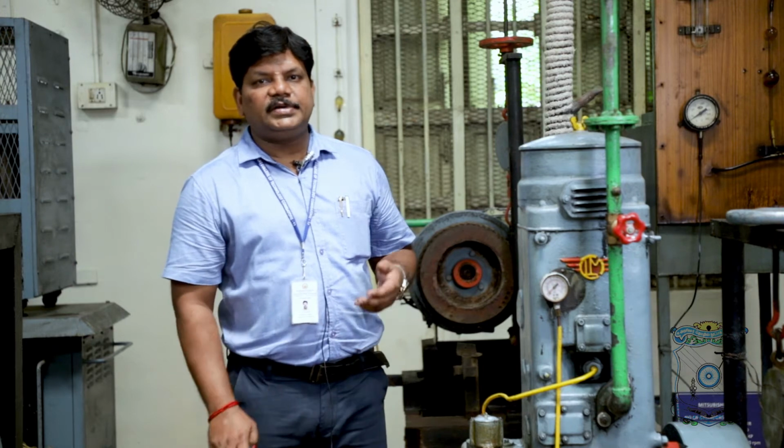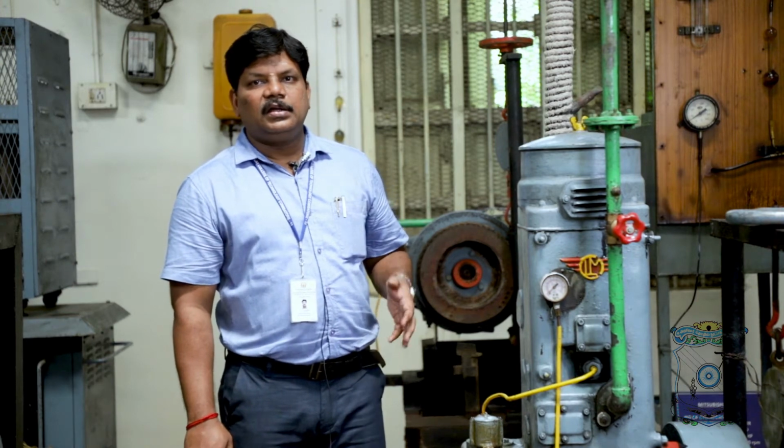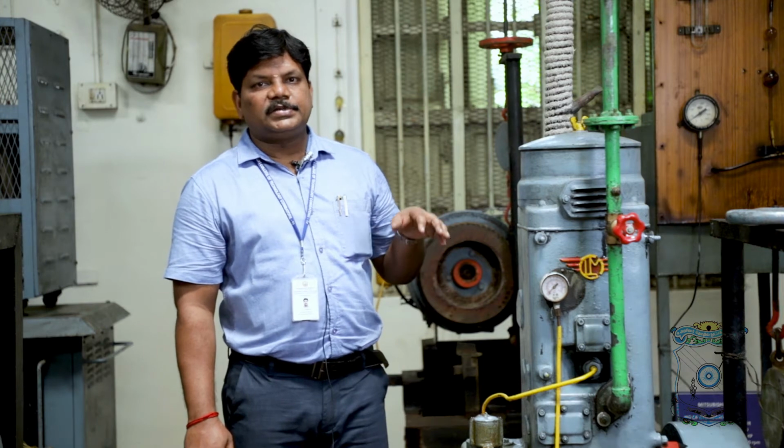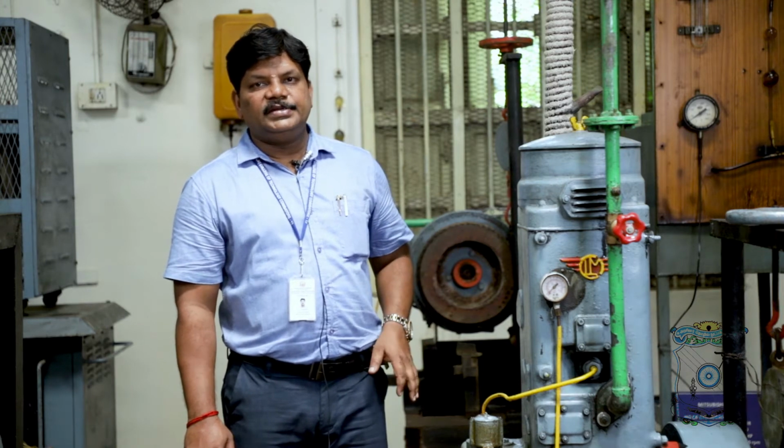From the maximum load, 75% of the load is taken for maintaining the load as constant. For 75% of the load, we have varied the speed with the help of this speed lever, from 1500 to 900 rpm at an interval of 100. Then for each and every speed, we measured the fuel consumption. That is, 25 cc of fuel consumption is considered, and for that 25 cc we measured the time, that is, how long it takes this engine to consume 25 cc of fuel. So we have measured that also.